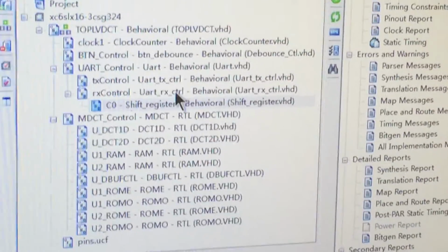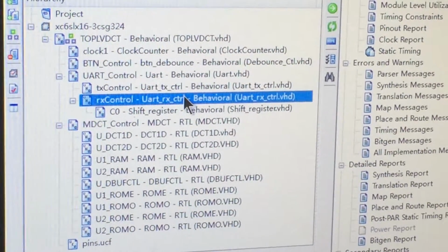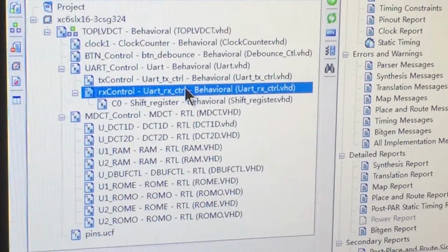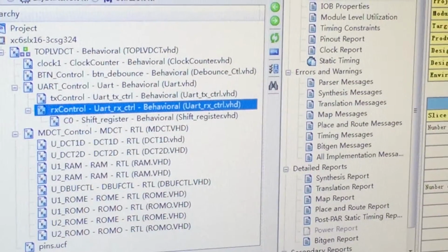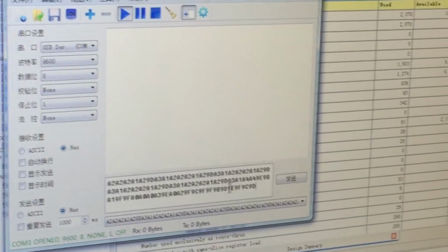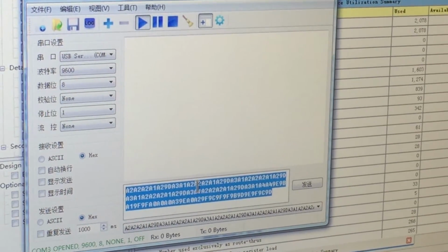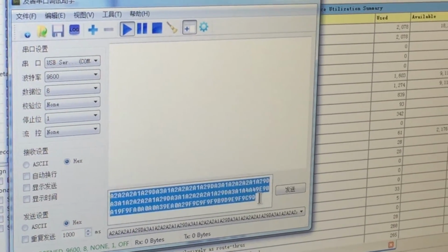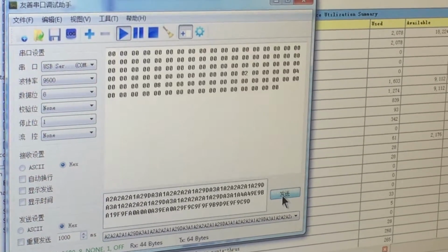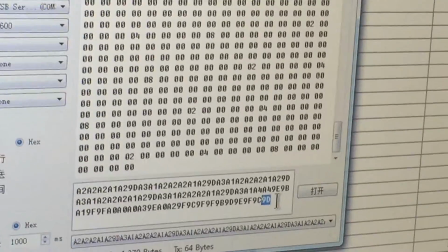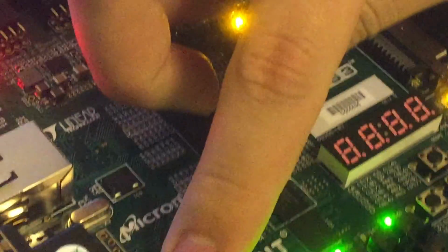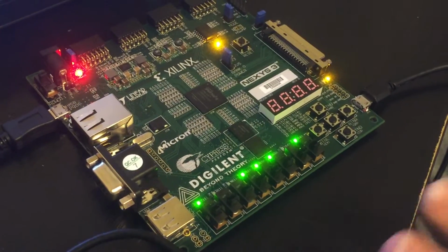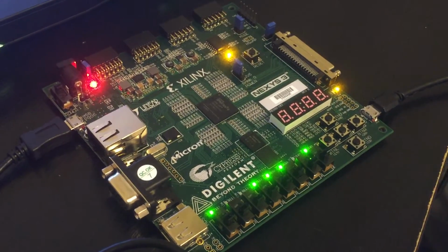And when we are trying to demo on FPGA, we consider using UART to build the communication between FPGA and the PC. And for the receive part, it works fine, because you can see here we are trying to send one block of image data into our FPGA, and I press this one and I stop here. You can find that the last byte I transmit is 9D, and I use LED to show that this one is 9, this one is D. So the receive part is good.